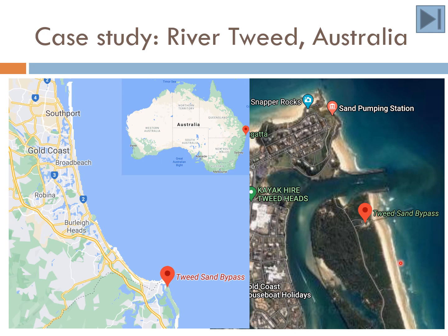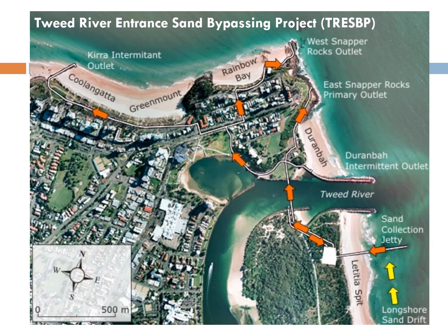The natural lateral drift is such that the sediment will move in the northward direction, and so in this case the sediments are intercepted here at the jetties and they are being pumped to the down coast section and deposited in this region so that the sediment is able to reach its downdrift section without passing through this waterway. This is a close-up view of the sediment bypassing system.